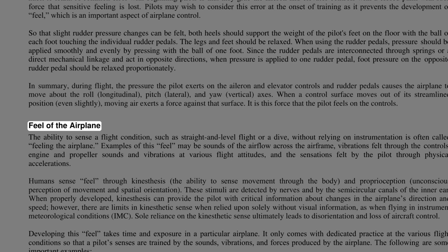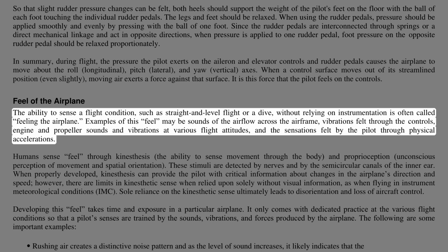Feel of the airplane, the ability to sense a flight condition, such as straight and level flight or a dive, without relying on instrumentation, is often called feeling the airplane. Examples of this feel may be sounds of the airflow across the airframe, vibrations felt through the controls, engine and propeller sounds and vibrations at various flight attitudes, and the sensations felt by the pilot through physical accelerations.